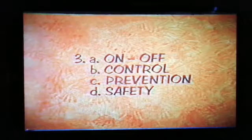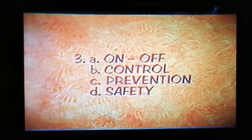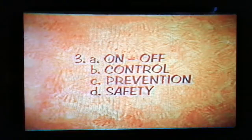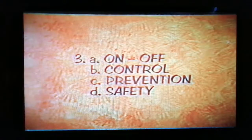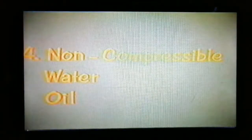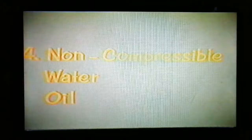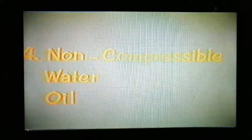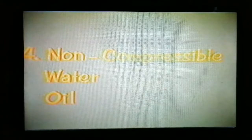Number 3, valves can be designed to cut the flow on or off, control the flow rate, prevent flow reversal, and provide safety of equipment by allowing overpressures to relieve. For number 4, relief valves are for non-compressible fluids, such as water and oil. On the other hand, safety valves are for compressible fluids, such as steam and other gases.